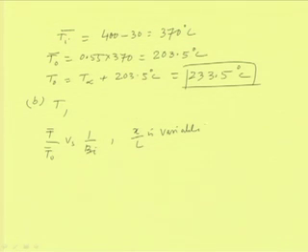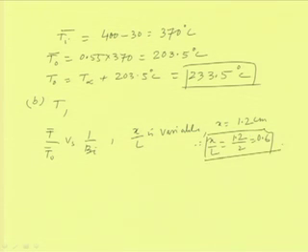That means, in this case, x is equal to 1.2, as we have shown, that is 1.2 centimeter. So, x by L for this case is 1.2 by 2, which is equal to 0.6. So, for x by L equal to 0.6, and already we have seen the expression for 1 by Biot number. 1 by Biot number we already know is equal to 21.5. This value is also known to us.